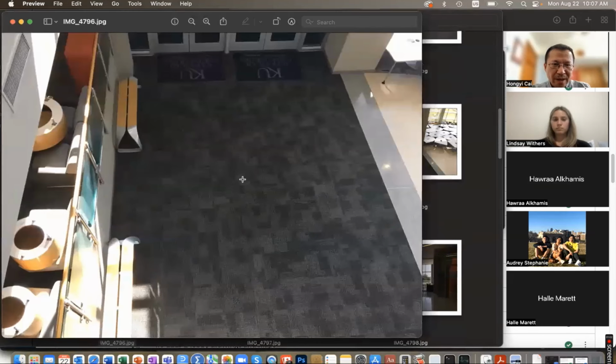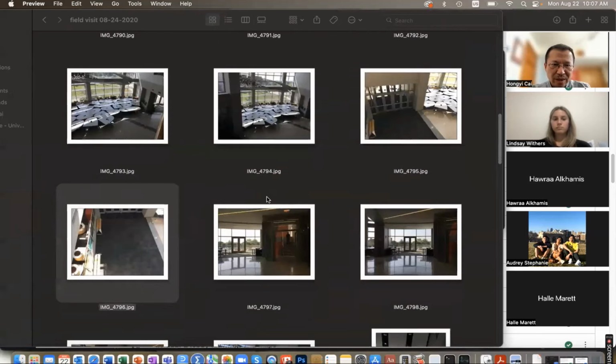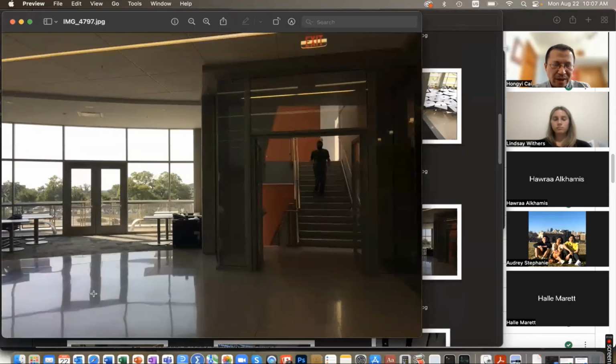Carpet. They are dark carpet, right? So dark carpet will have less light reflection, but this is only for this portion. On the other side of the space, you will have a lot of concrete floor, which will have a little bit higher reflection, but also will give you a mirrored image of the outside, which may cause confusion and glare in a severe condition, like if you have a dark sunbeam shining on the floor, you may have some glare, right?